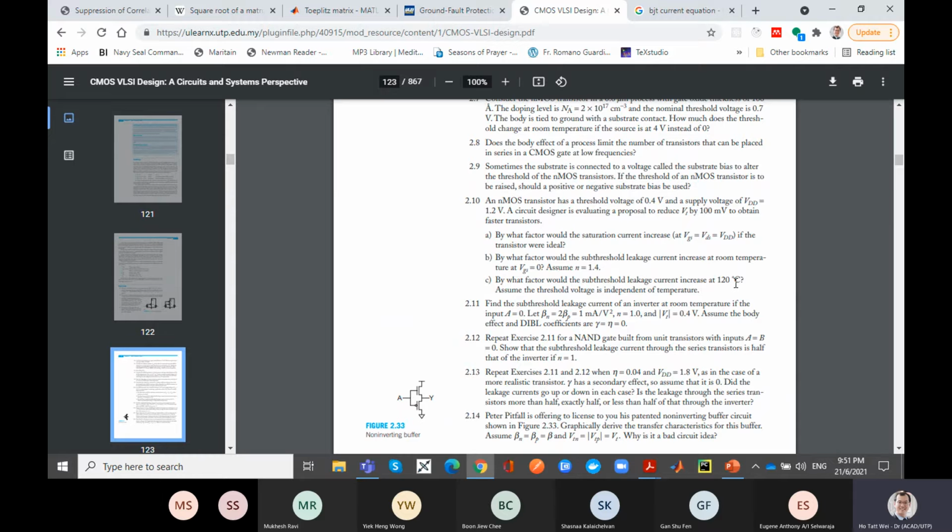If you change the temperature by 10 degrees, by 20 degrees, by 30 degrees, which you can do because it's a very small chip with a very small area, and I have some current, it's going to heat up. Or if I have some variation in my VTH, my threshold voltage, how much does my subthreshold leakage change? Because this is what's going to actually matter in the real world. This is how those numbers will change. Okay, Ken?